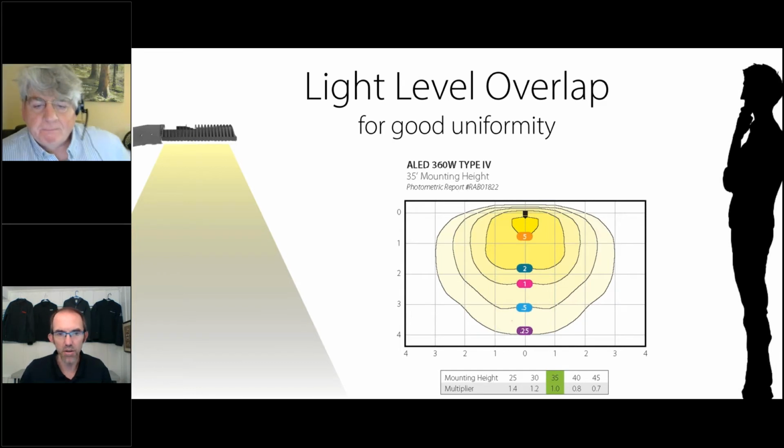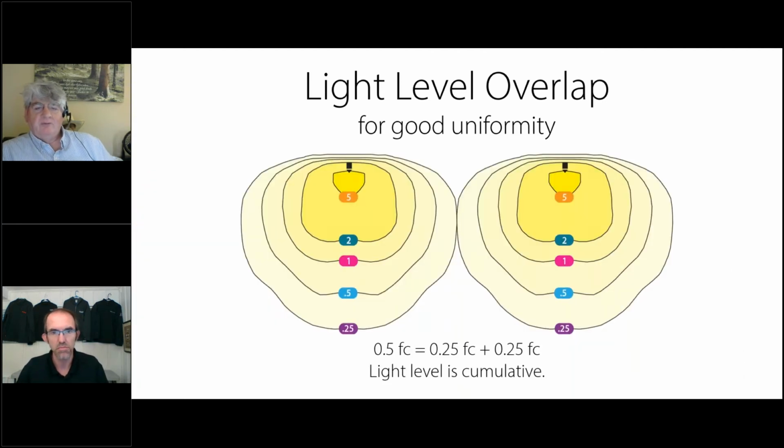So without pulling out a photometric report, pulling out an IES file, going to EasyLayout, we can use this layout here, or this isometric chart, and do something with it, right? Absolutely. We can get a rough idea of, and this is actually the way things were done in the past. You would take and trace that and trace them all over your plan by hand. You can take and look at overlap.